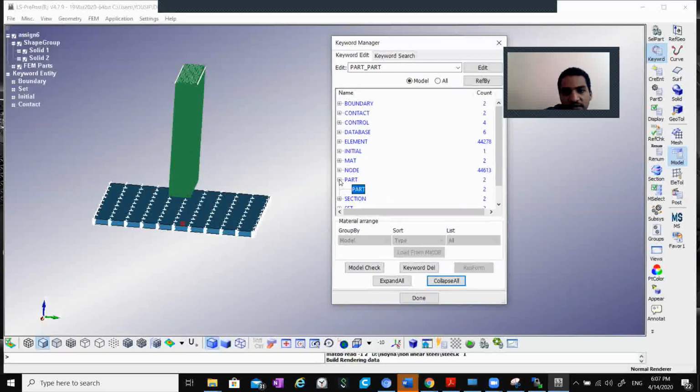And then after that, you go to velocity initial. So you set the velocity for the nodes that you did. And after that, we go to contacts. So you determine the contacts. So now we are saying these nodes will have a contact with this body. And you can see all of this